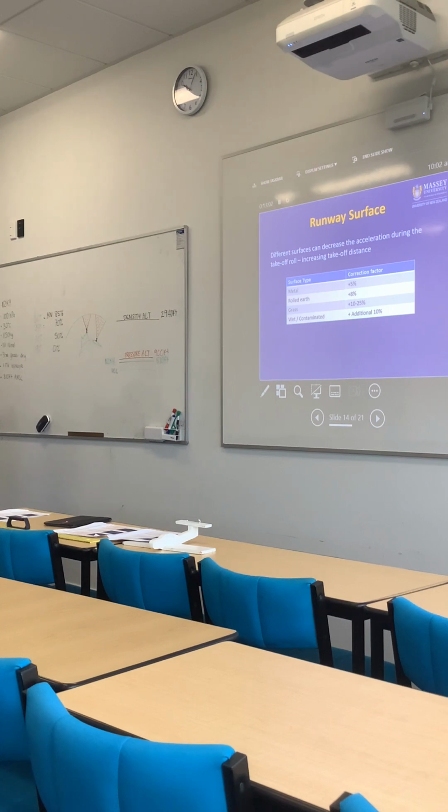Have a little bit of a discussion here about why these things increase the distances. Okay, it's all about friction, poorer acceleration. Those are key words to use on this slide. With wet runways, if they've ever driven a car into a puddle and felt the deceleration, I liken it to that. So poorer acceleration, longer distance. So the worst combination is wet, long grass. So we've got to be very careful to account for those things. Potentially there, if it was wet and long grass, we might have to add 35% onto our takeoff distance. Huge.